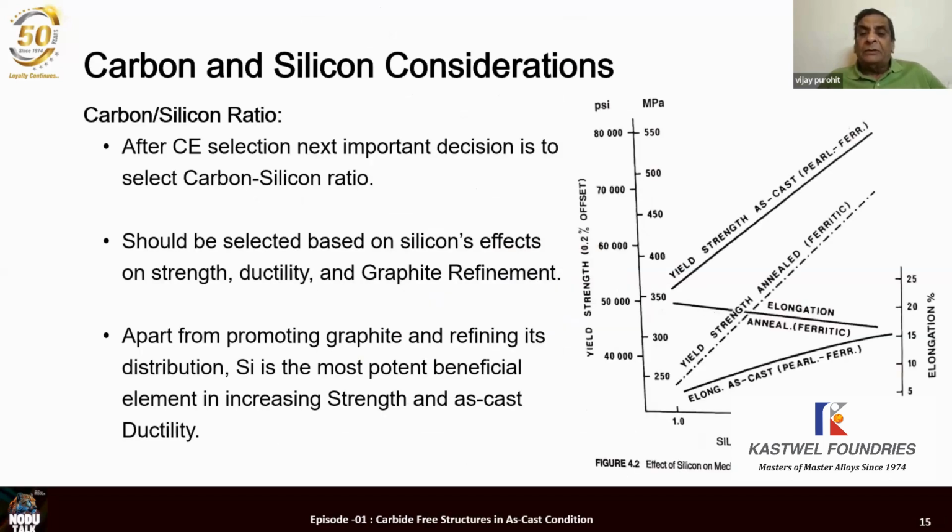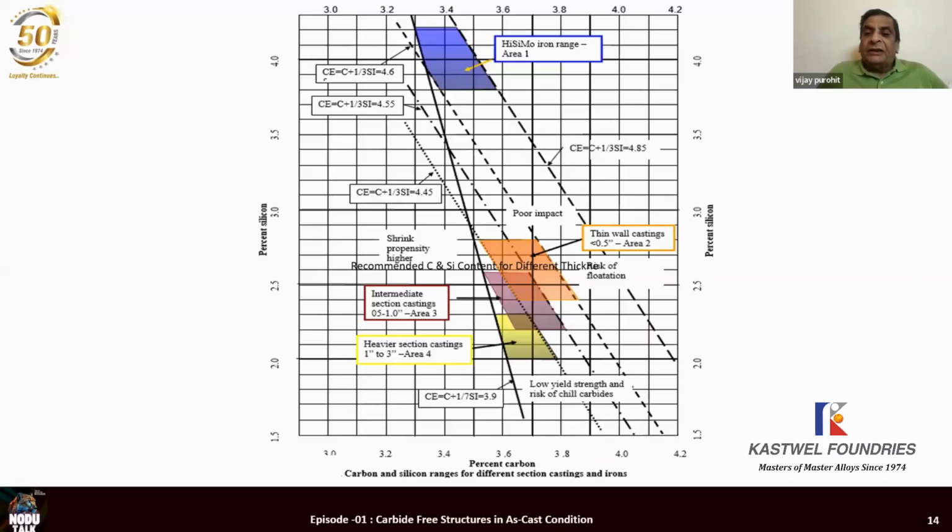So carbon equivalent, no, the previous slide, please. Yes, the carbon equivalent CMO grades, because these are all thin section castings. They are normally used for turbocharger engines, turbocharger housings, turbocharger exhaust manifolds, and many more high silicon and moly containing castings, which are thin wall castings.